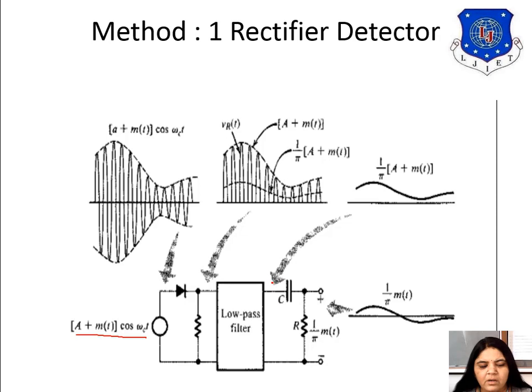Again, we want to remove that component also. So this DC value we can eliminate by passing it through the coupling capacitor. After passing through the coupling capacitor, we can have the output across this resistor, having a 0 DC value. So this is the calculation that we need to perform.